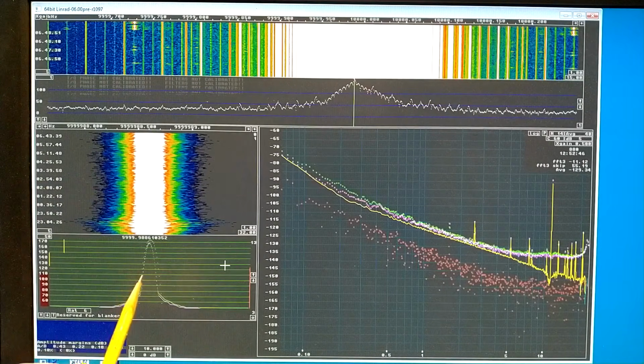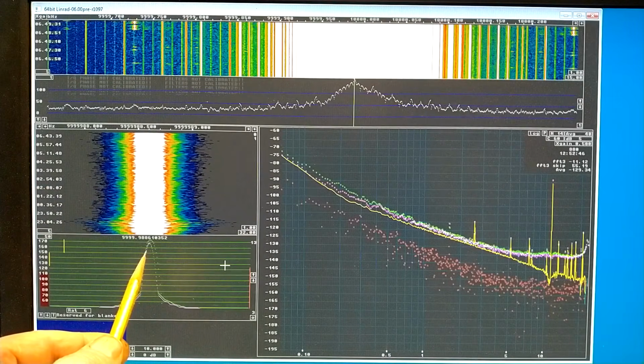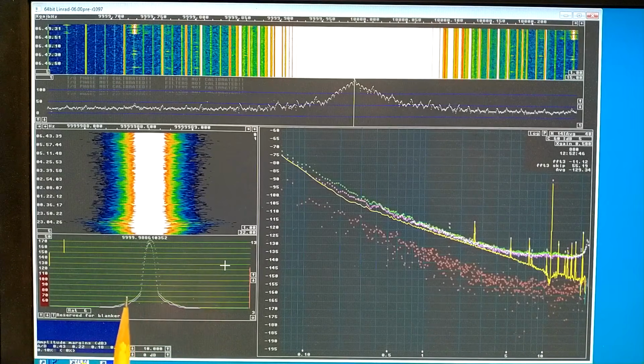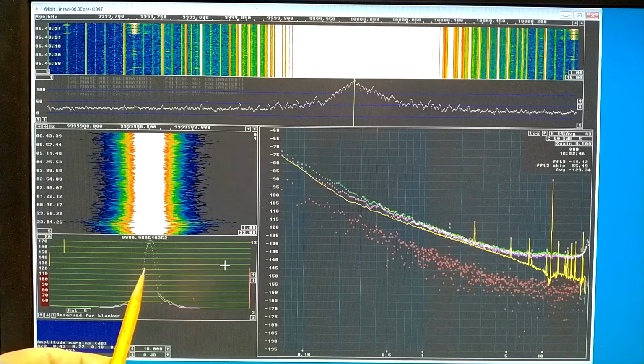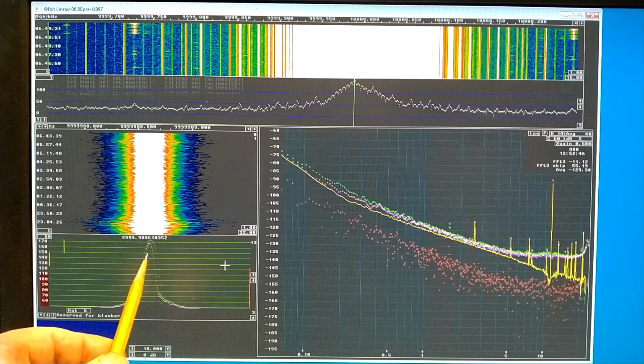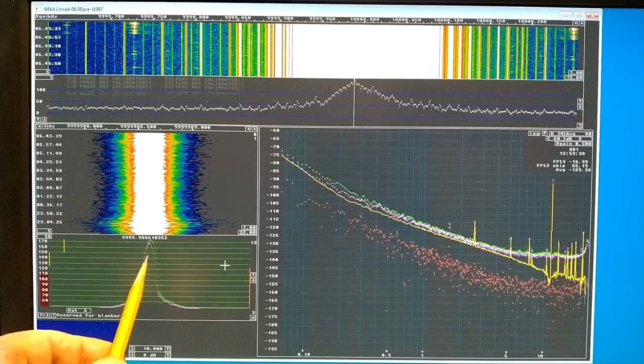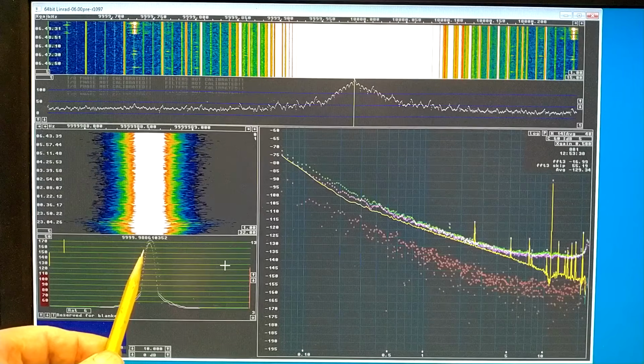The carrier that comes out through this narrow filter is multiplied with the entire bandwidth, and that creates an I and a Q signal, and if the phase is not shifted by the filter, the amplitude modulation comes in phase and the phase modulation comes 90 degrees.